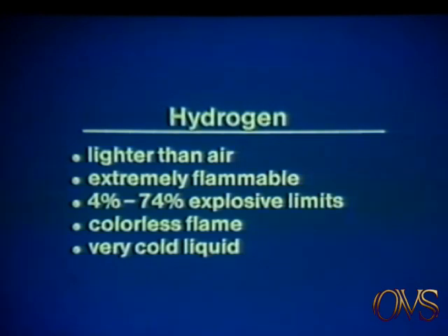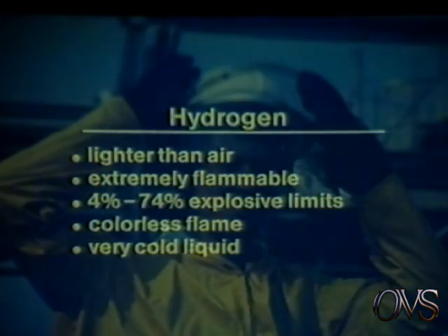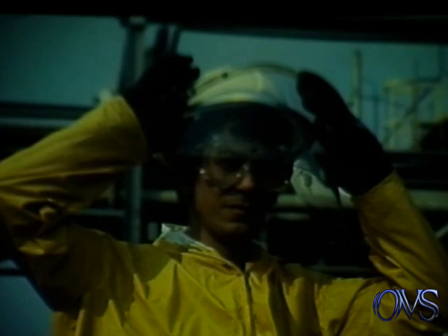Since H2 isn't liquid until below minus 423 degrees Fahrenheit, the freezing effects are a major hazard. Wear chemical goggles, a face shield, and loose protective clothing and gloves if you have to work in the vicinity of liquid H2. Since H2 isn't toxic, any first aid for contact will be in response to the freezing effects of the liquid.